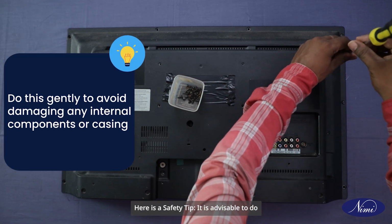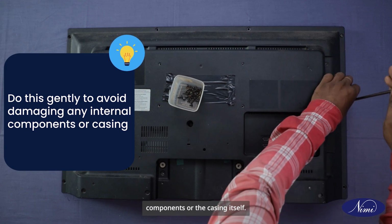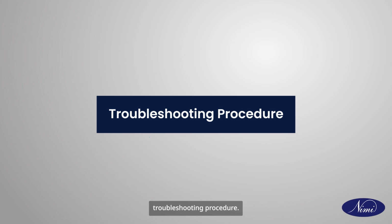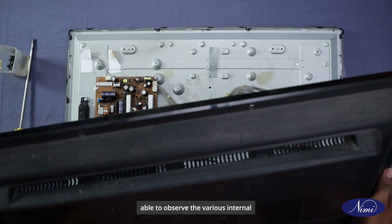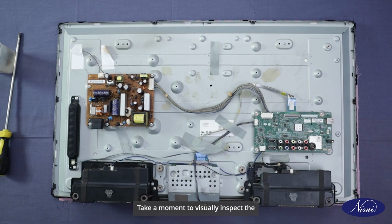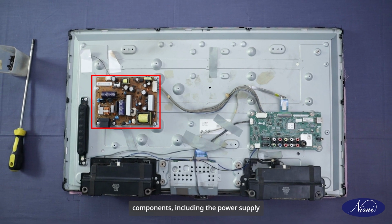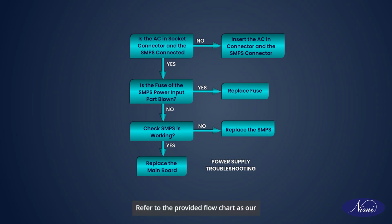Here is a safety tip. It is advisable to do this gently to avoid damaging any internal components or the casing itself. Next, let's get into the troubleshooting procedure. Upon removing the back cover, we are now able to observe the various internal sections of the LCD or LED TV. Take a moment to visually inspect the layout and condition of the internal components, including the power supply board, main board, and connection cables. Refer to the provided flowchart as our guide for systematic troubleshooting.